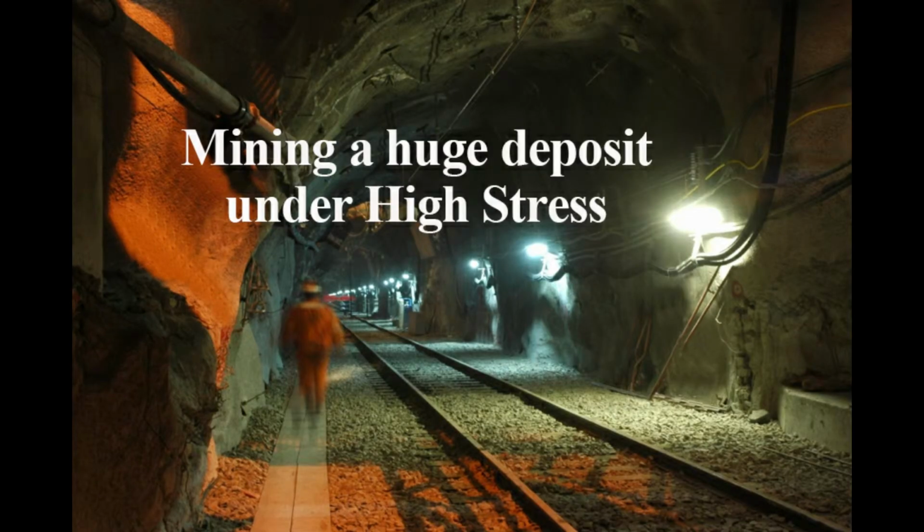Next, what will happen if we mine a huge deposit where the stresses are high? When we are mining a huge deposit upon which there is high stress, following are the consequences. There may be a rock burst, or there may be subsidence. The cracks may move, and if the rock is weak, spalling will occur, or the roof may collapse.